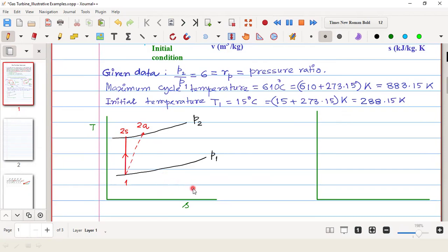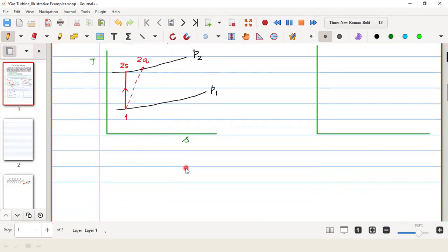So what is the meaning of isentropic efficiency? During process 1 to 2, there is some enthalpy change. So basically, when the work done is calculated, we calculate the change in enthalpy. So during this process, the work required for the compression is H2 minus H1, that is H2s minus H1. Now, during the actual process, it is more, as you can see. So here, due to the deviation, what happens basically